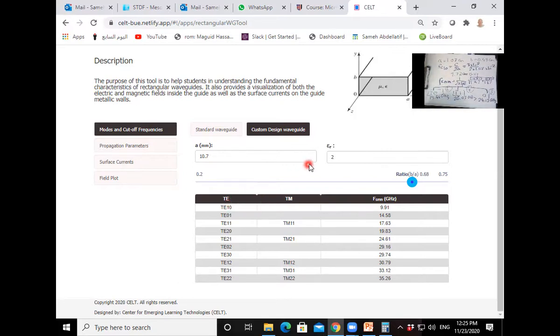So very simple. Here you have TE01 and then TE11. Let's go, for example, to this case. Oh, yeah, now the sequence changes. Again, TE01 is the second, but TE20 becomes the third, and TE11 becomes the fourth. So you can adjust the sequence of your modes based on the ratio between B and A, which is the main concept I'm trying to deliver in this example: the sequence of your modes is controllable through the ratio B over A.